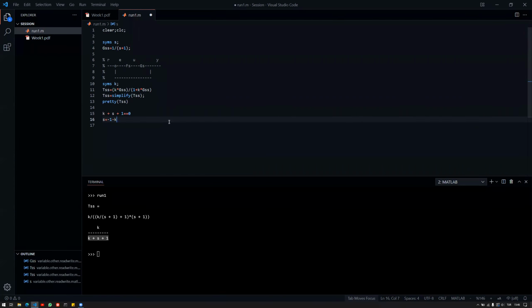Sometimes you have some requirements of closed loop systems. For example, I want to have a certain settling time, a speed of response. I want to have certain frequency behaviors. So there are more limitations to designing a controller. But since this is a basic controller, a p-type controller, a static gain, the first step for me is to try to get an interval, at least, for the controller parameter K, so that I will always end up in stable closed loops. So this is one thing.